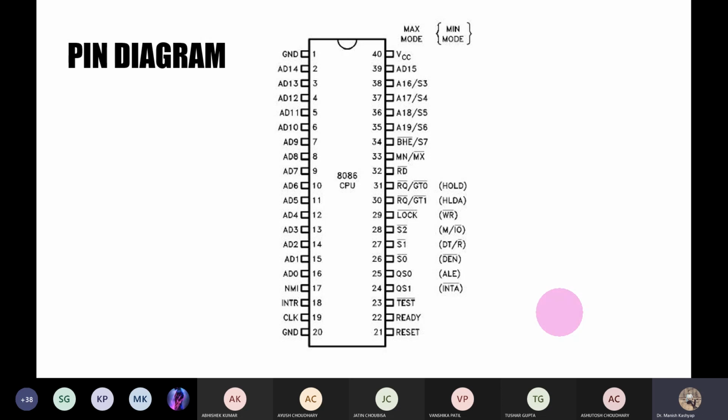Voltage is not an absolute quantity. Voltage is a relative quantity. So this ground pin is usually taken as a zero reference voltage. It might have some positive or negative voltage depending upon whatever is applied to it. But in reference to this ground pin, the VCC will have some additional voltage or some lower voltage, which will be called its voltage. So voltage is a relative term first of all.